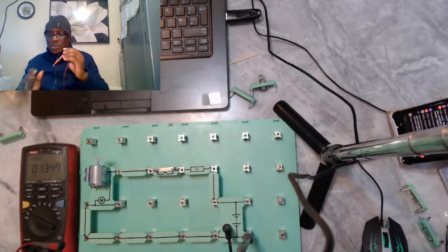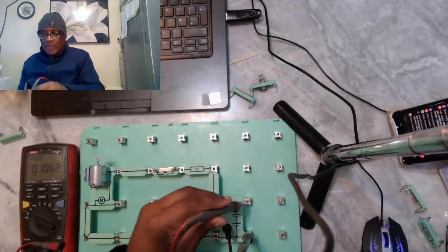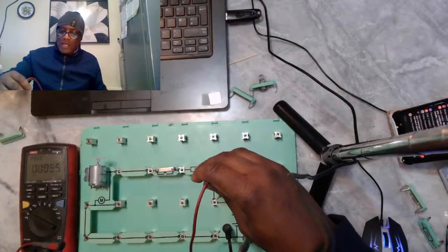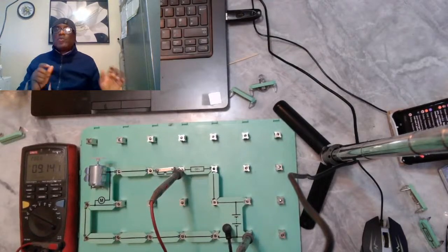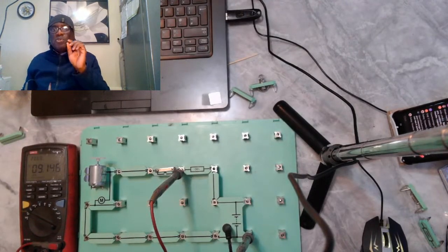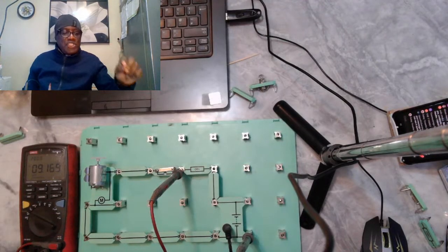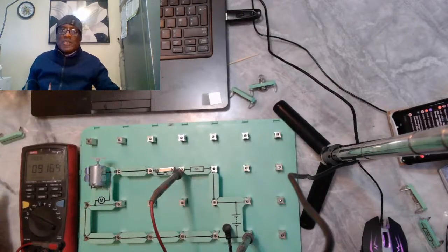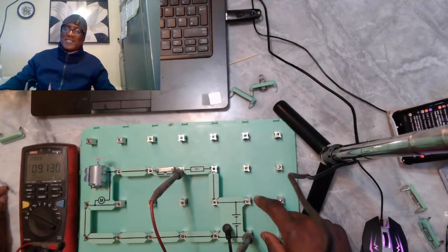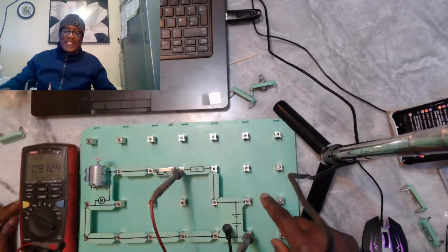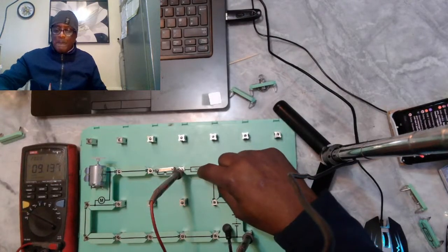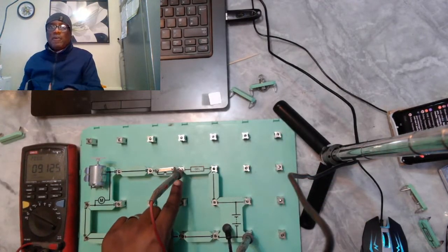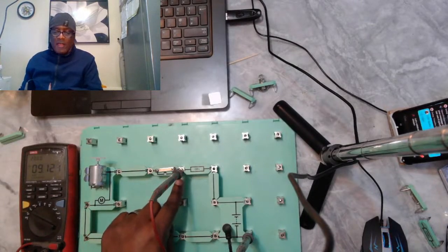So once you start to check the two sides, you come here, you have got your voltage, you come here, you have dropped voltage by 2. That's why I'm saying it is important to you, technician, to make sure that you check your battery voltage first. Please check your battery voltage first. That's the only way you can pick up these voltage drops. We have a voltage drop there from,